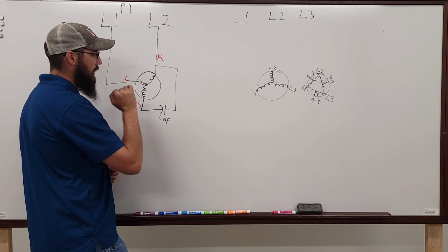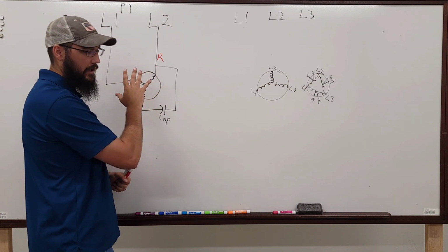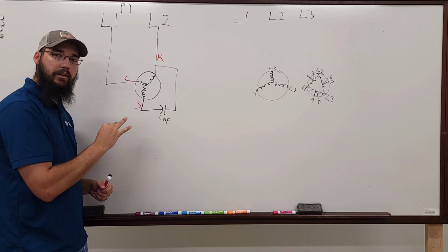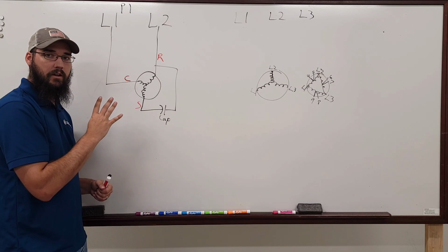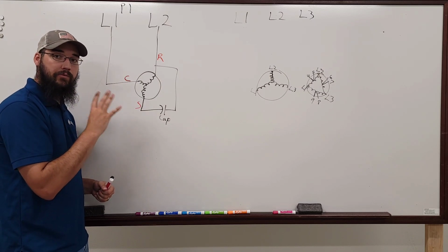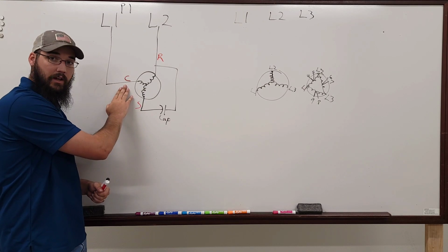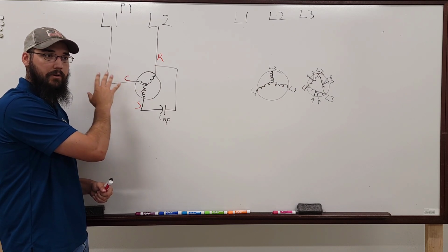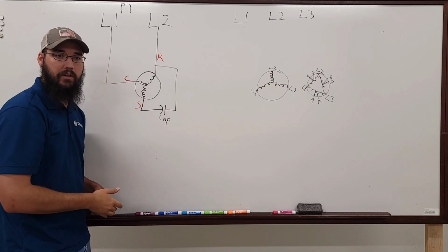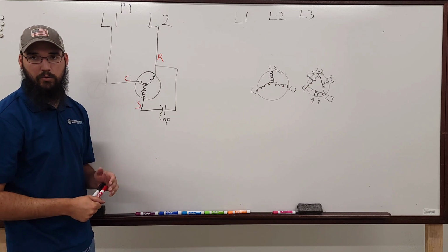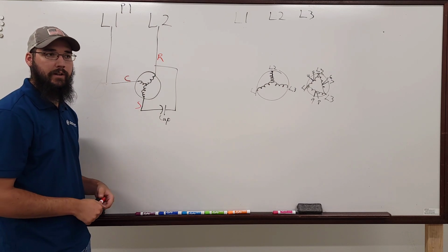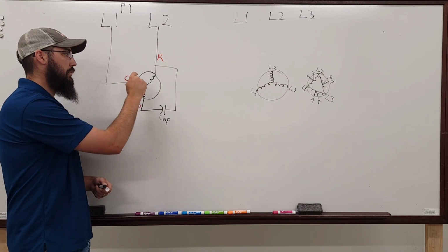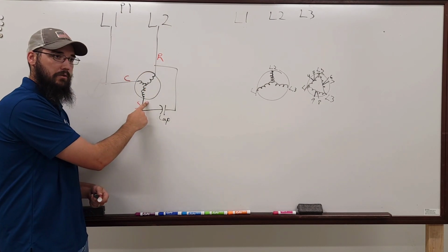So there are 2 primary methods of motor configurations. You have a 3-wire and a 4-wire. Okay? In discussing 3 and 4-wire, we are not talking about the speed tap. I don't care how many speed taps you got, it could be 3, 4, 5, 6, whatever they chose for that particular day. Now, honestly, they're usually no more than 4. But point is, that's not what I'm referring to. What I'm referring to is how many power wires are running.